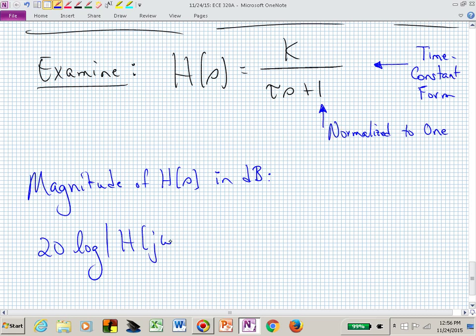And now for the frequency response, we are actually walking up the imaginary axis in our S-plane and evaluating the magnitude and phase at each of those frequencies omega. We don't want to do that piece by piece by piece for an infinite number of omegas. With your calculator or otherwise, you want to have some strategies for sketching these a little bit more quickly.